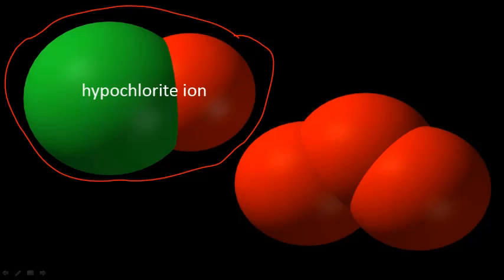The basic principle is that adding this to water will oxidize pretty much any of the remaining organic matter, which will kill most of the bacteria or the other microbes that might be remaining even after secondary treatment. The problem with this method is the oxidized byproducts of chlorination aren't usually great chemicals or great things to have in appreciable quantities in water. So there's some concern over the safety as to how much of this kind of stuff we actually want in our water.